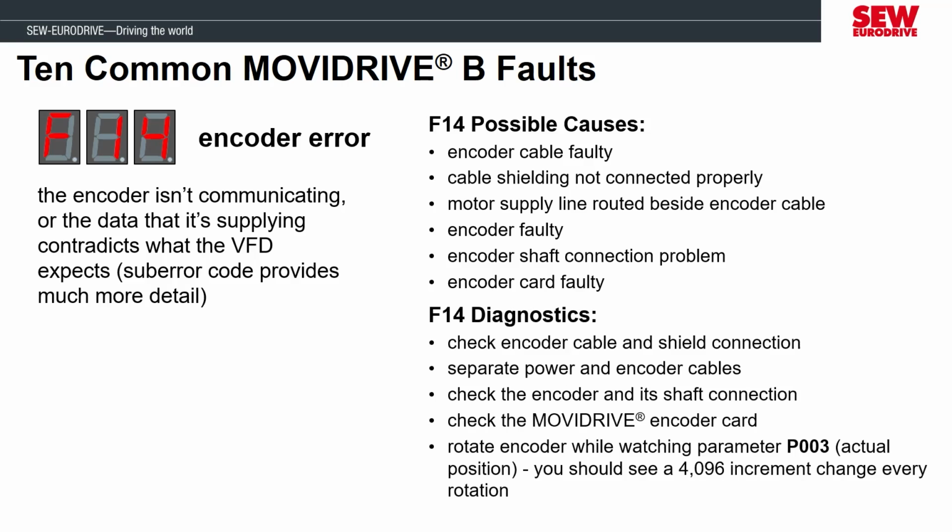If you're getting this error and it's intermittent, then there could be issues with electrical noise from high voltage cables, a worn encoder cable, which is common for cables that travel with the application, or the encoder signal fluctuates, which can be caused by power supplies dropping during travel, slipping mechanical connections, or damaged areas such as a barcode tape for encoder barcode scanners. If the F14 error is persistent and doesn't reset, then inspect the encoder cable for damage and check for loose connections.